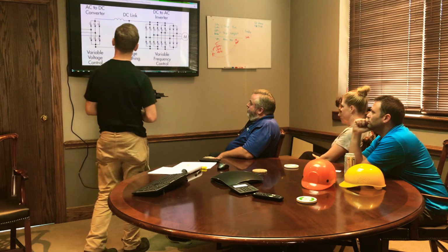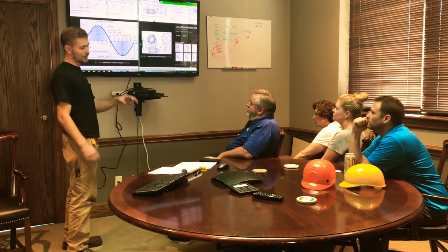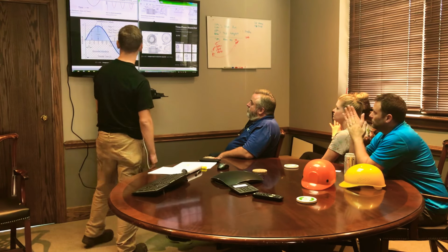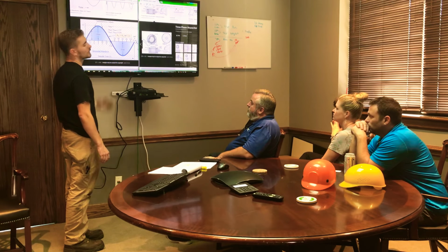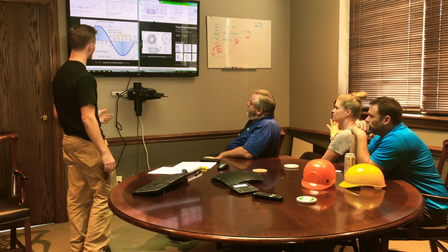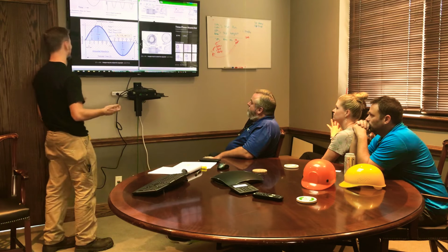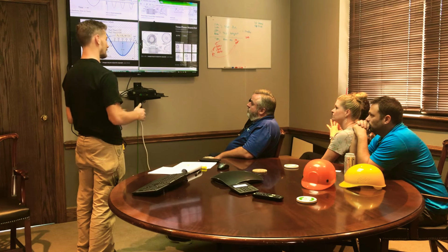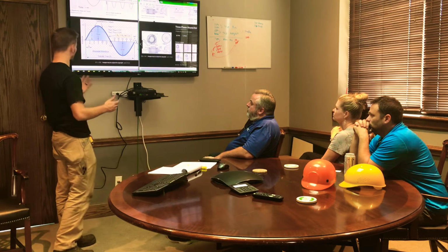So the first thing that we will discuss within this topic is frequency. We're going to discuss frequency because it's a very, very important concept, and actually the key concept on how a variable frequency drive controls motors. Frequency is the number of times that alternating current goes from a positive voltage to a negative voltage in a second. So for common 120 volt American household electricity, you're going to see 60 hertz, which means it's going to go from positive 60 volts to negative 60 volts 60 times within a second. And the 60 volts, that just applies to 120 volt power, but if you're using 480, then your phases are going to go up and down to a different voltage. So again, frequency is very important.